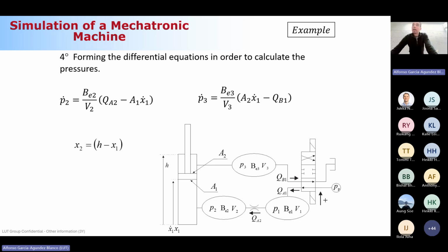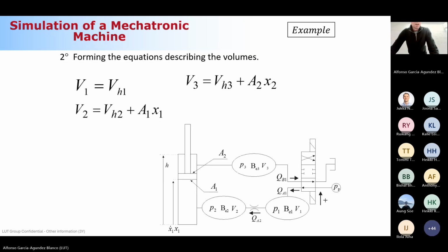Do I have that term here? Yes, because the piston is moving and control volume 2 has part of it inside the chamber. So I have to take into account that final term, the time derivative of the control volume. Let's go back. Control volume 2, V2, was given by this, no? If I write the time derivative of V2, this is a constant, so 0.